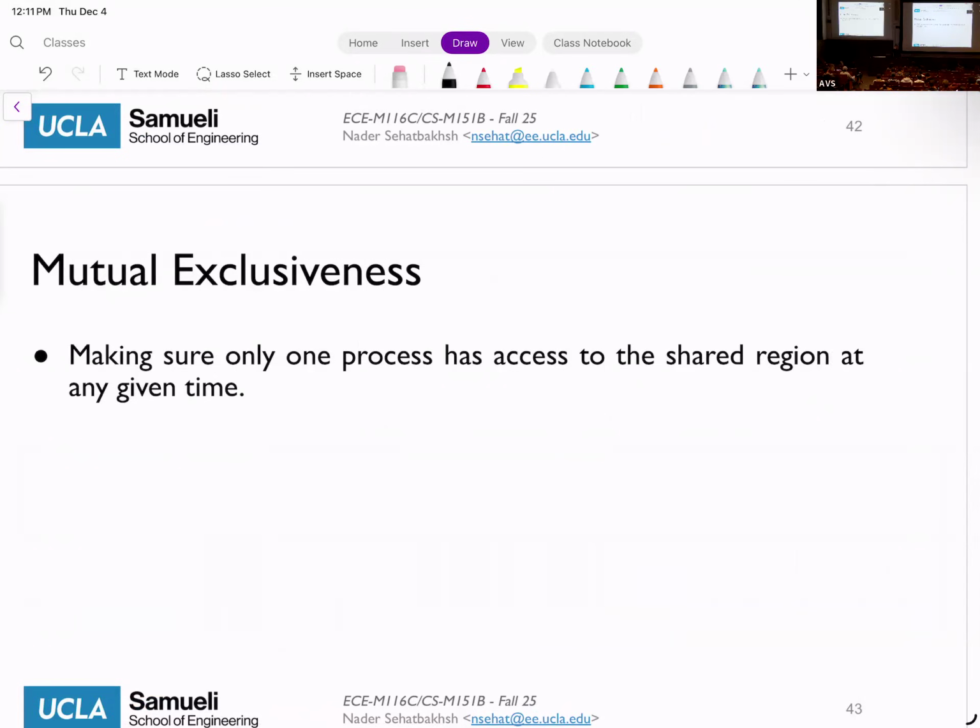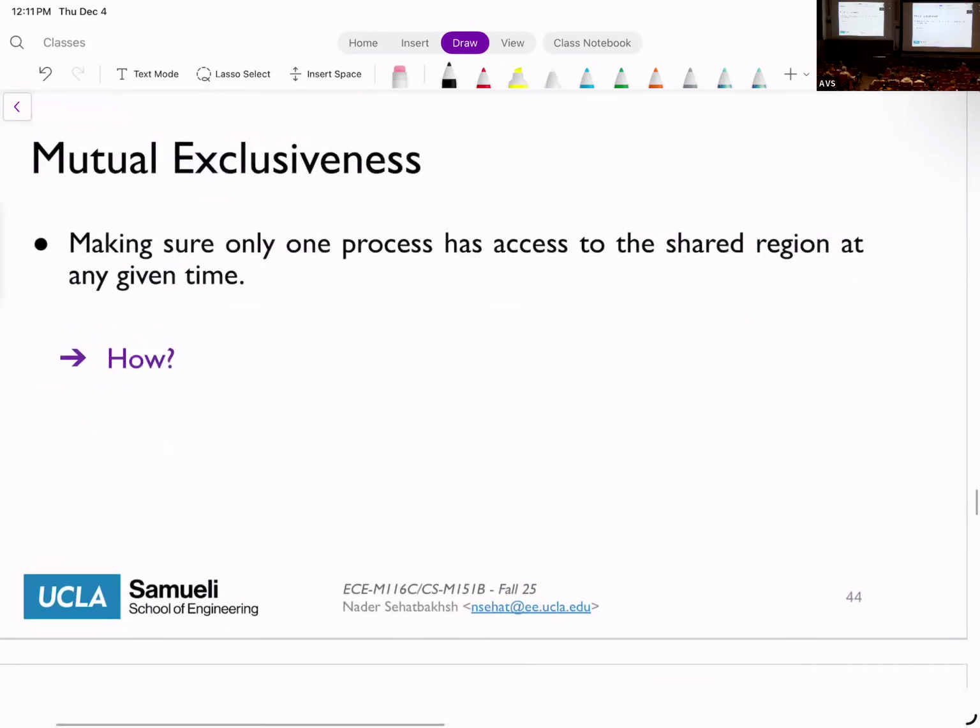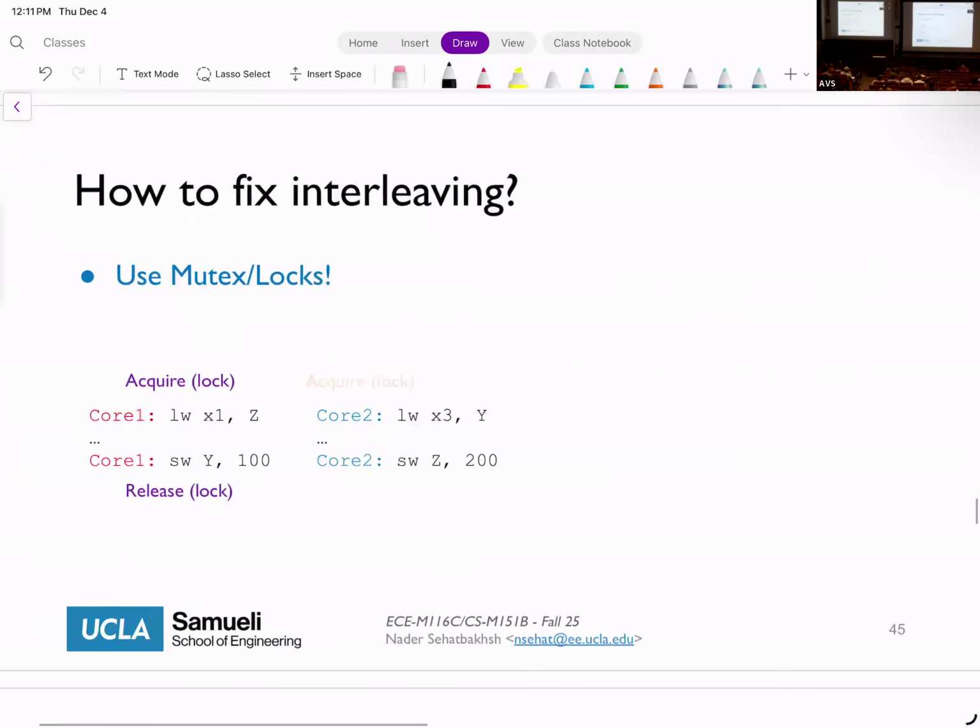There is one variable or sequence of variables that you're really worried about. What you do is put that into this mutual exclusiveness region, where only one of the cores can write at that point. So you guarantee that if someone is reading and writing that section, all the others cannot read it, write it, or do anything with that region of the code. This is usually implemented as some form of a lock.